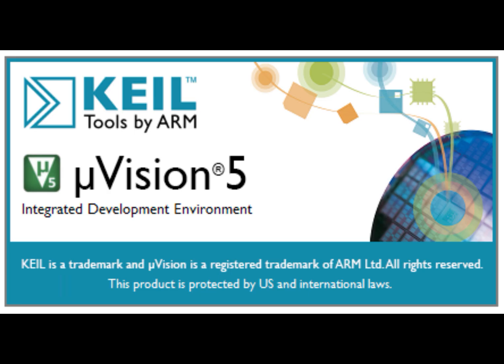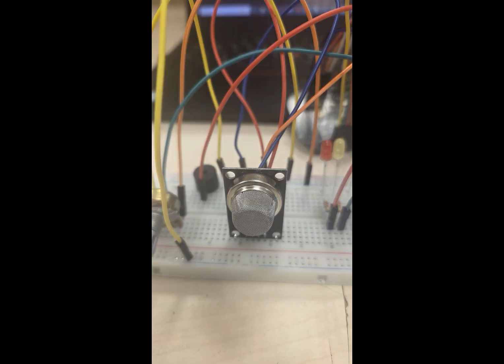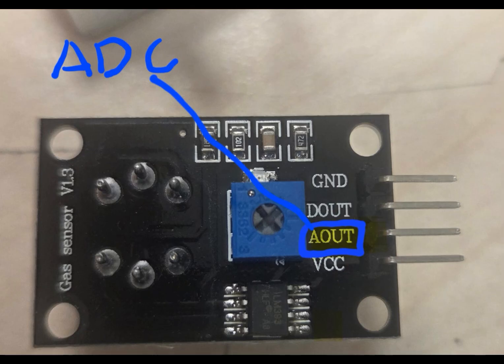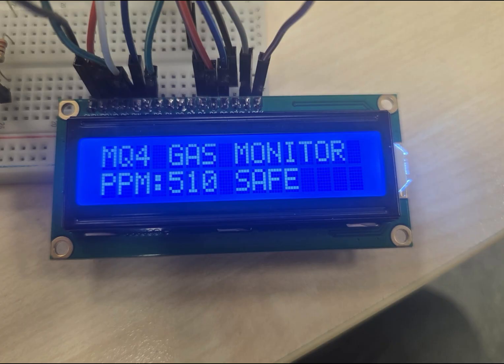The main sensing component of the system is the MQ-4 gas sensor, which detects combustible gases and produces an analog voltage output proportional to the gas concentration in the environment. This analog signal is connected to the ADC input of the microcontroller. For user feedback, a 16x2 character LCD display is used. The LCD shows the current gas concentration in ppm, as well as the system status such as safe mode, warning